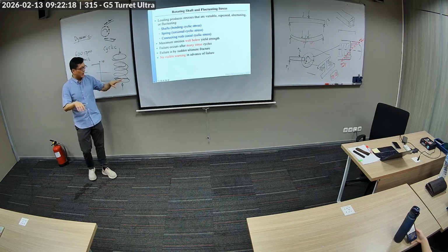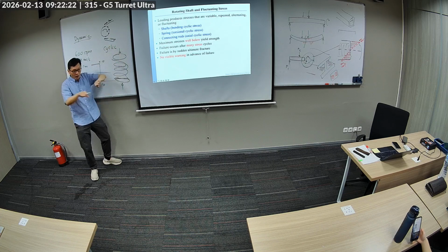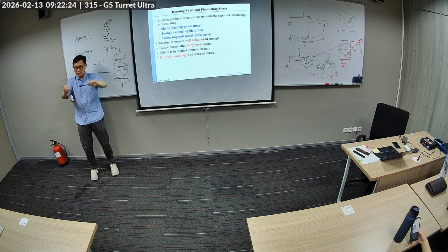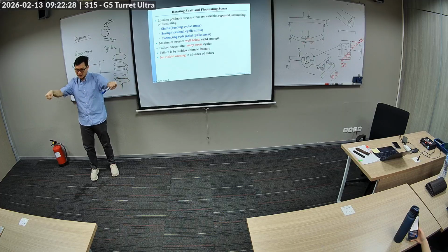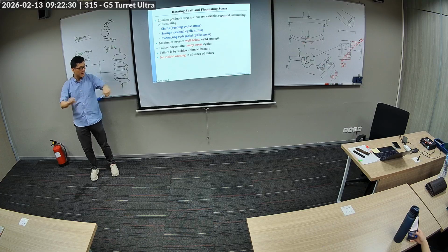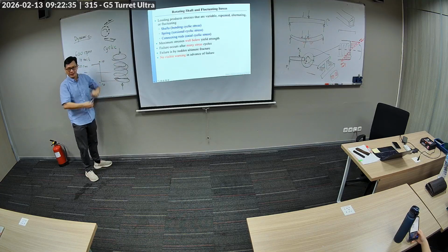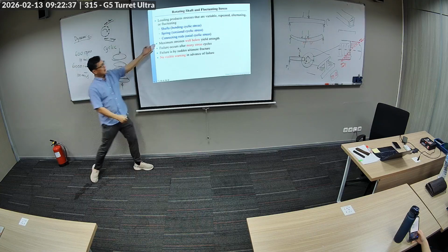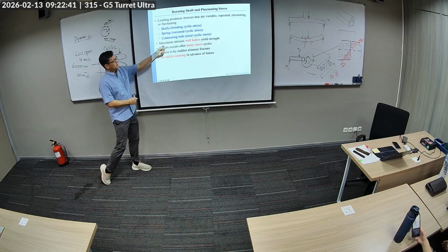But anyways, when you cycle a spring like this, you're not cycling like this on the wire. If I open it up as a wire, you're not doing that. You are doing that. So a spring under dynamic loading, you're actually doing this. So it's actually torsional cyclic stress.